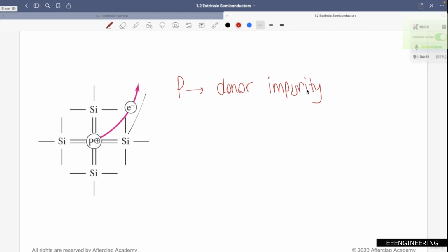And the thing in here is that as a result, when a donor impurity is added to the semiconductor, free moving electrons are generated, because logically we have silicon from group 4, which has 4 valence electrons. But this time we are bringing another atom having 5 electrons in the valence shell. Therefore, this causes one electron to be free and moving in the crystal.